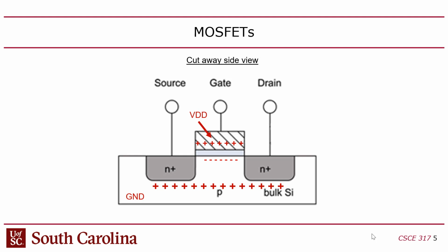Now you might say, why does that matter? Who cares? The reason this is relevant is because the speed at which circuits run on a computer chip, the whole clock speed, logic propagation delay, Moore's law, all of that depends on how fast this transistor can switch. And what you're really doing with these transistors is you're charging and discharging gates. The source and drain are charging and discharging gates of other transistors, right? Because this is a logic gate ultimately that's feeding into other logic gates, right?